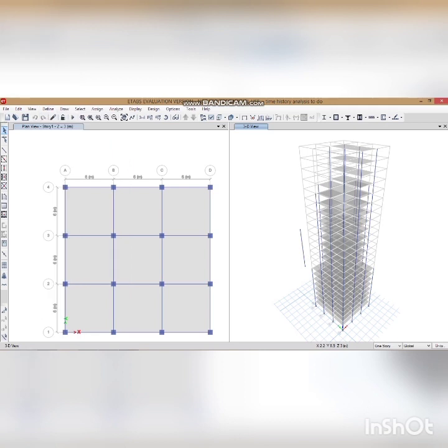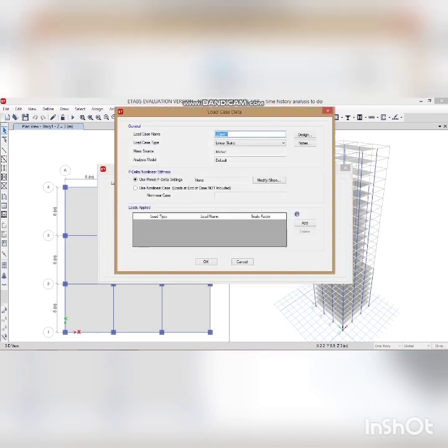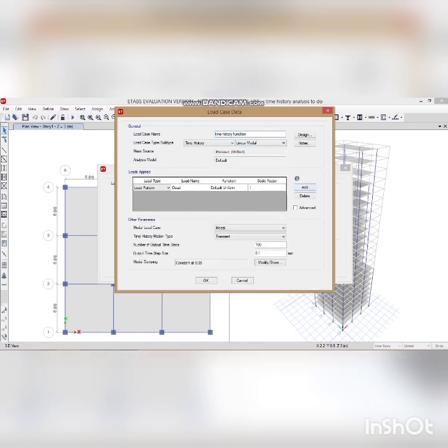Wait for the design check to take place, and now after the design check has been done, the software asks you whether it can reiterate the frame sections. Click on OK, and then if it still asks whether it can reiterate any of the sections which need reiteration, click on OK. And after all the sections have been reiterated, even if there are still members which are failing, then you need to redesign the dimensions of the sections. That is pretty simple, you know how to do it. You can unlock the model and change the dimensions of the particular members which are failing.